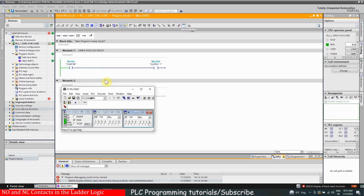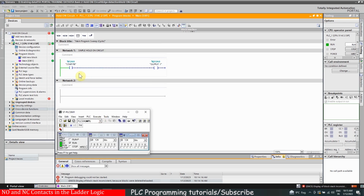So this is a very straightforward and simple logic. Next thing I want to do here is hold on our output Q124.0, which means that if I only press this start push button once and release it, the output Q124.0 should get latched on and remain on.